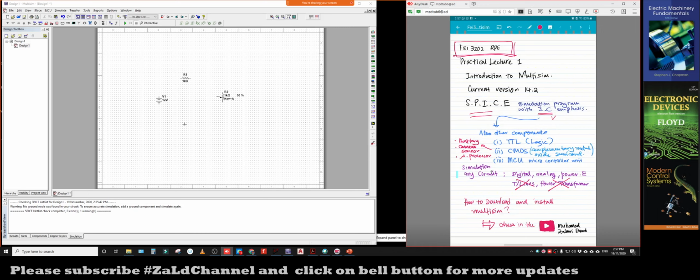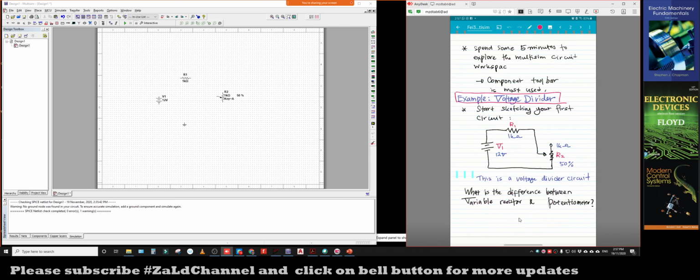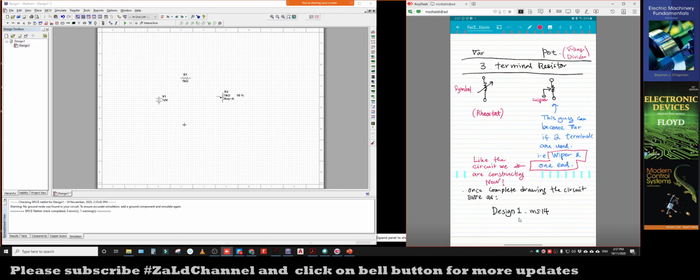So before I do the wiring, let me explain a little bit about the difference between a potentiometer and a variable resistor, as you can see in the handwritten notes here. In terms of symbol, it is different. This is the symbol of the variable resistor. The other one is the symbol of the potentiometer. It has a wiper in the middle. So basically this potentiometer can become a variable resistor if we connect the wiper and the other end.